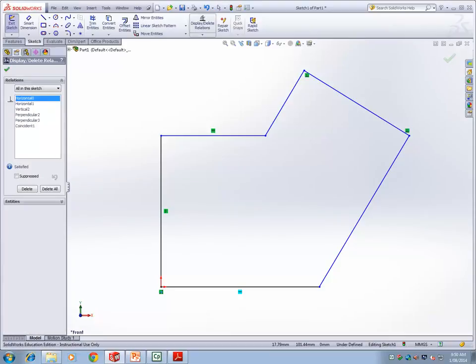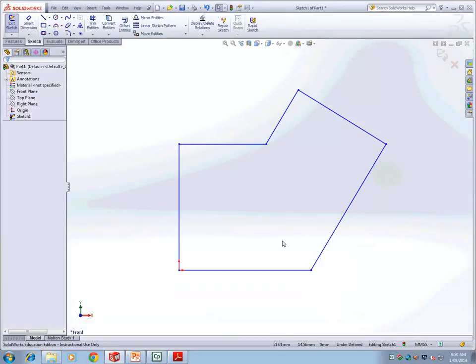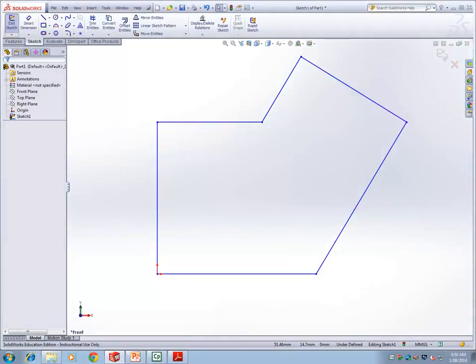Okay. If you wanted, you can delete all of them and add new relationships. So in this case, I can delete all of them. I can keep adding them if I wanted. This is mostly a custom defined. As I deleted all the relationships, what happened to the sketch now? They're all undefined. They are underdefined. So you got them into a blue. Black is best on the sketch.